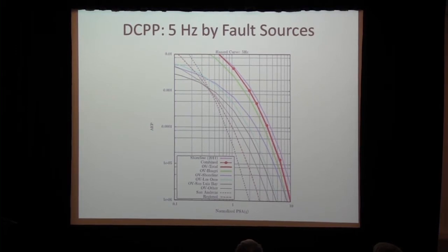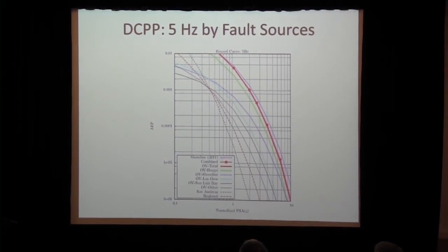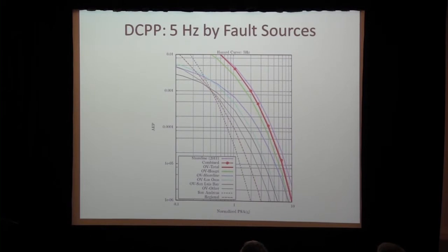And part of that, if you remember back, Steve gave a presentation talking about the weighted slip rate for the Hosgri fault. If you compare that value, I think it was 1.8 or so, 1.9, to the Shoreline report, the weighted value for the Hosgri slip was about 2.25 millimeters per year. So the slip rate on the Hosgri, which is the most important fault, has come down, so that makes sense. The next curve down, which is a red dash with the big red dots, that's the combined. Now the combined is including 40% on the OV model, 30% on the Southwest model, and 30% on the Northeast model. So that's now combining the three tectonic models and the preliminary logic tree for the SSE. And you can see it's come down relative to the Shoreline model.